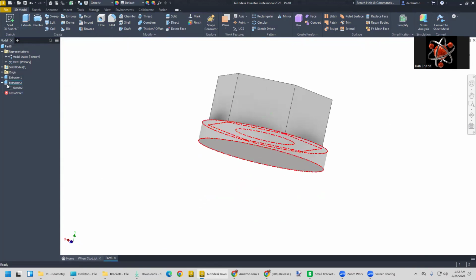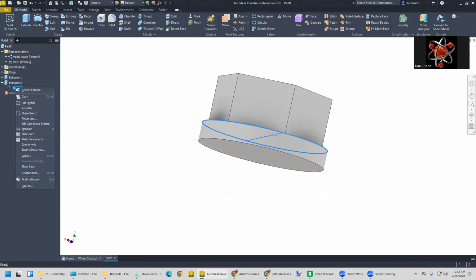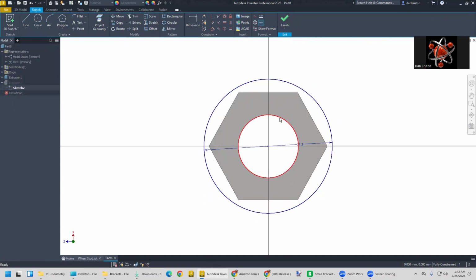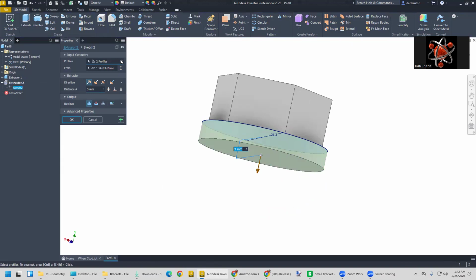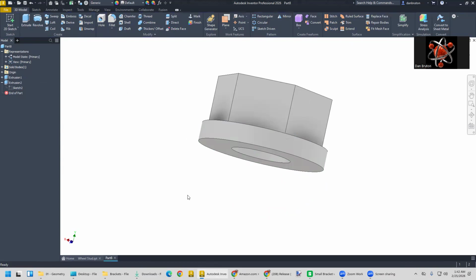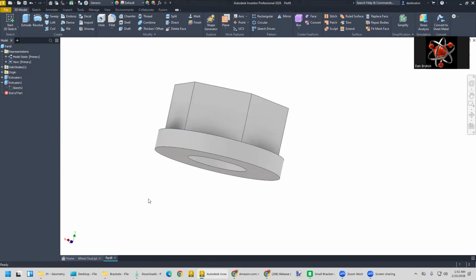But what we got to do on this one is we got to come back here to the sketch, edit that right here, edit the sketch, because we need to have this circle also included as part of our extrusion. So go back to the sketch, project the geometry of that circle out here. Then you click OK, and you can modify your extrusion so that it excludes that central portion. Edit feature. You go up here and say delete the profiles, select the donut. There we are.